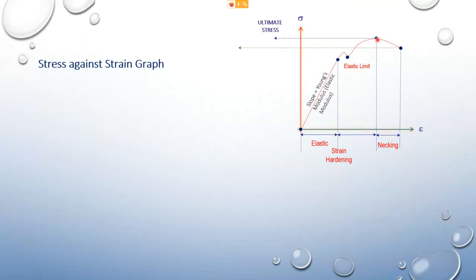Okay, the ultimate stress: from this point, you draw a straight horizontal line across, and it touches the stress axis. So that gives you a value, which is the ultimate stress. Remember, for any calculation work or any design work, we are not advised to use this value straight away. We usually use the ultimate stress divided by a factor of safety in order to get the allowable stress. And then here, that is your rupture stress.